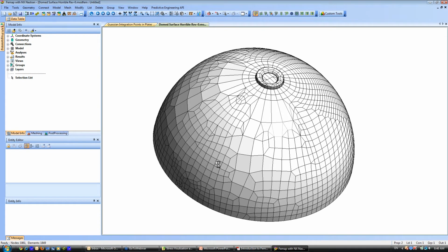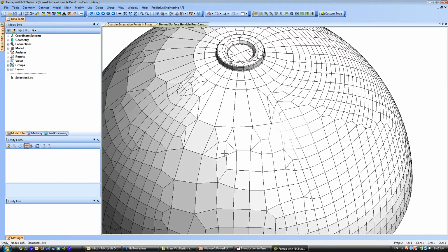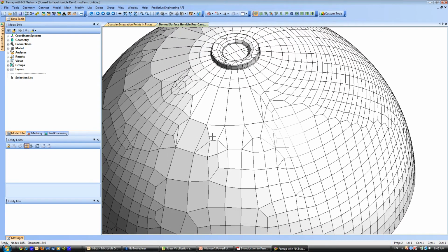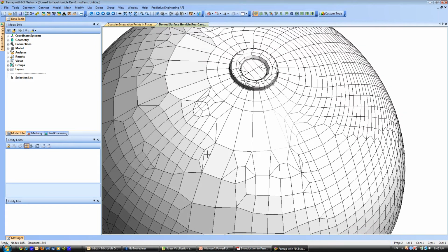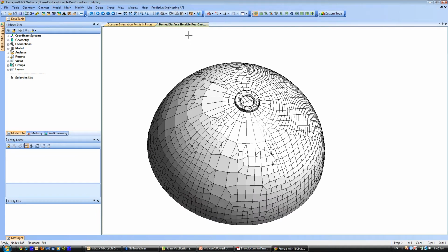And then you look at this and you got to shake your head going, this can't be good. And you just look and you just wonder, how is Gaussian integration going to put points in for something that's so distorted, element quality? And you think about it, it has to place low Gaussian integration points, and it has to break it up, and you have these triangles here, and you just know that can't be the best mesh.